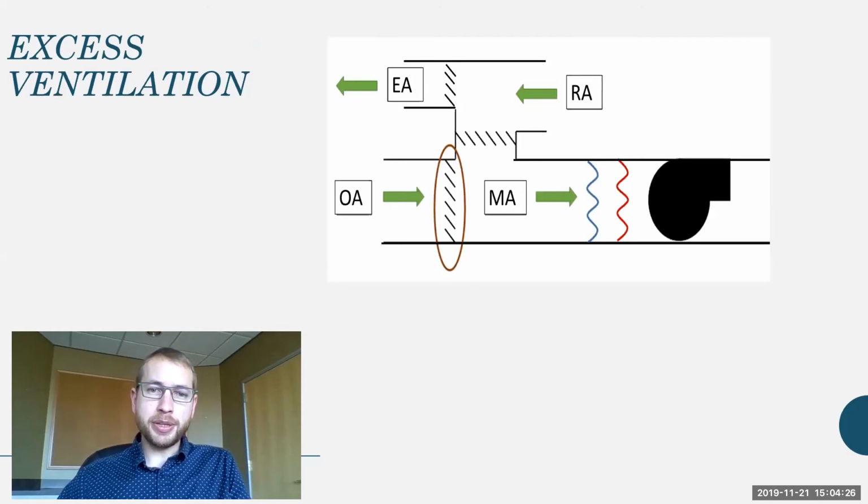The other thing that can happen is the outdoor air damper can get stuck open, right? These vents can get jammed, or maybe the program has been overridden. It's great to have fresh air. I'm all for it. Sometimes these can get programmed shut all the time, which isn't all that great for the people working in there. So make sure that it's still providing a minimum amount of fresh air, but you don't need to be providing fresh air for just the carpets and the empty chairs in the office at night.